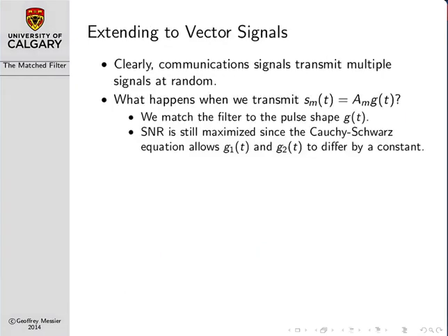So what we went through in the previous slides was basically a very quick summary of the standard matched filter derivation that you can find in most undergraduate textbooks. And the reason why it's called the matched filter is because, as we saw, the response of the demodulator filter is basically matched to the shape of the desired signal.